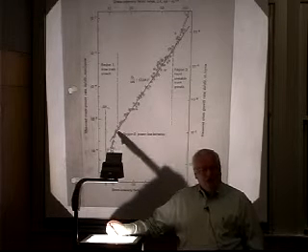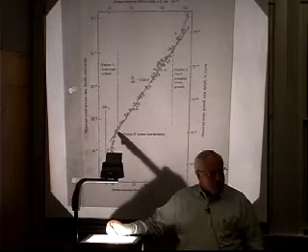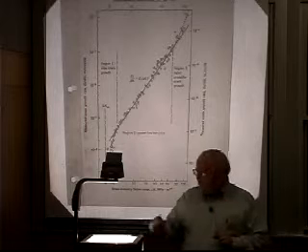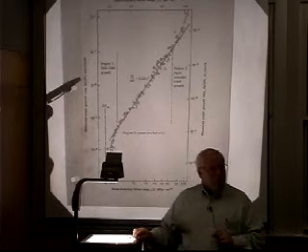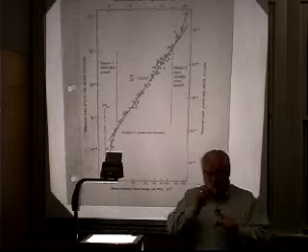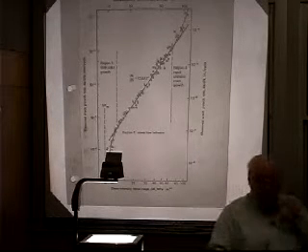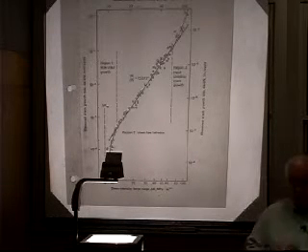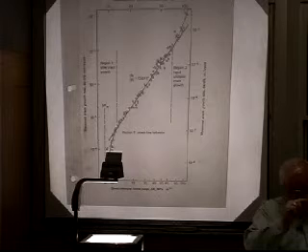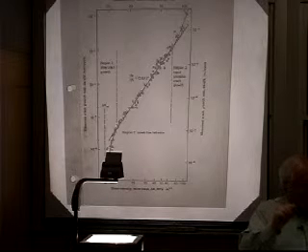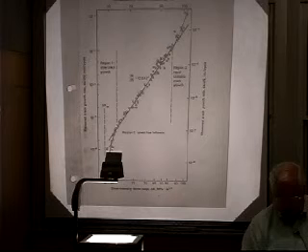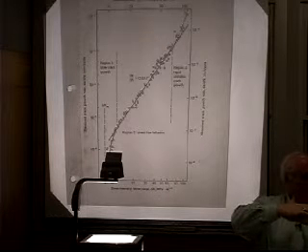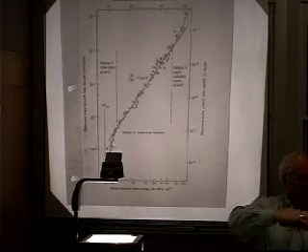But I can generate this curve in about 2 weeks in the machine, because what I'm plotting here is the change in crack length a per cycle. And so I have some little sensor, and sometimes the sensor is nothing more than a little microscope and a light behind it, and I try to measure the crack length as it's moving across. I can also measure the crack opening, because as the crack gets wider, deeper, it opens more and more.